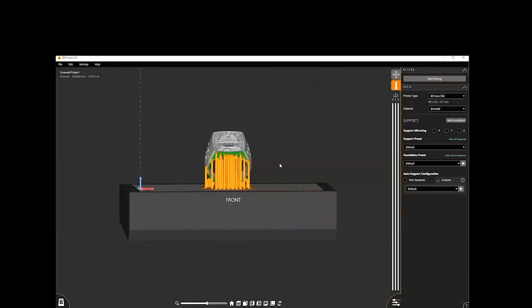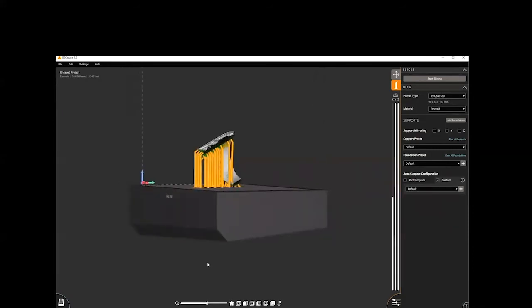The next thing that we're going to show you here is you'll see these X, Y, and Z long vertical bars here. This is called the slicing function, or not the slicing, I apologize, the sectioning plane. What this does is you can hide certain sides or parts of your model using the X, Y, or Z axes. This allows you to hide part of the model so you can get into certain parts of the model that you may not be able to see because other parts of it are in the way.